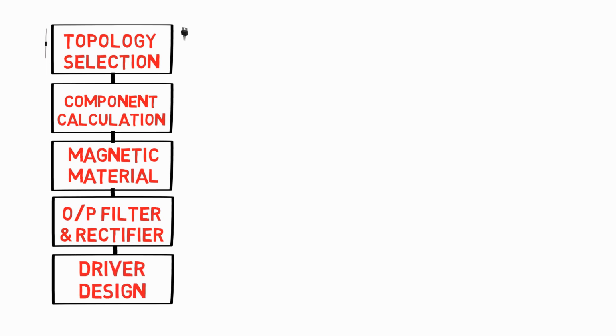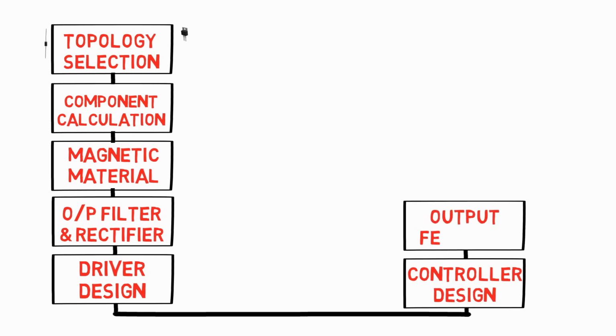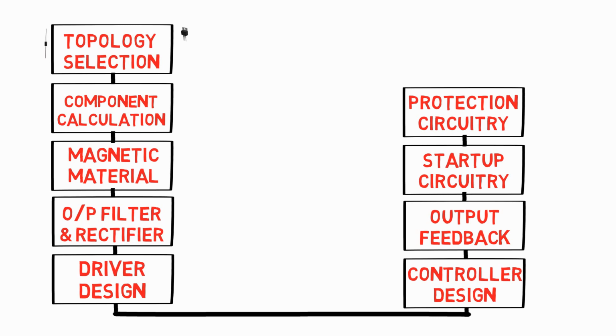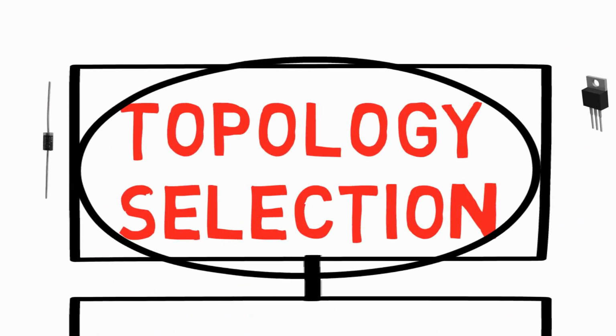Then comes driver design. Then there is controller design. Then designing an output feedback stage. After that, designing a small startup circuitry. Then we have to design some sort of protection circuitry to prevent the damaging of components. And last but not least is thermal analysis.